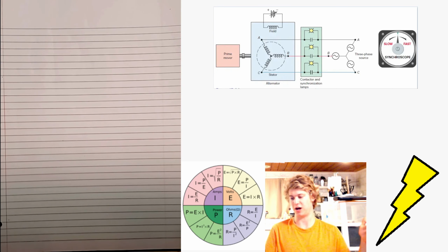Utility generators are often being connected and disconnected from a large power grid in response to customer demand. Such a grid is said to be an infinite bus because it contains so many generators essentially being connected in parallel that neither its voltage nor its frequency can be altered. Because, of course, when you're wiring things in parallel, you're just adding the amps and the voltage remains the same. And at the same time, you're technically lowering the resistance of the overall system as well. Considerable disturbance in the electrical system and damage to the alternator windings can occur if proper synchronization procedures are not followed.